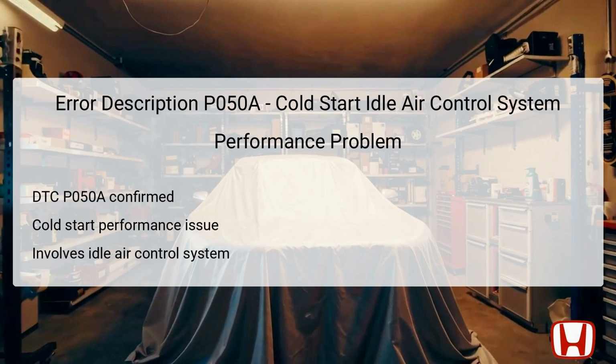The malfunction can lead to rough idling, stalling, or even difficulty starting the vehicle. It's often located near the throttle body, allowing it to directly control the air mixture entering the engine. If unexplained performance problems occur, further investigation of the idle air control system and associated sensors is warranted.